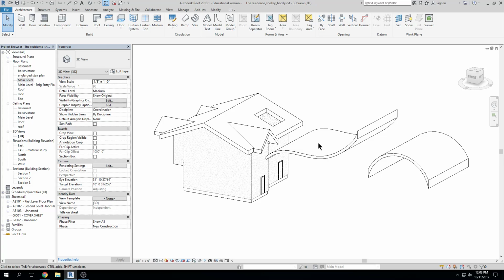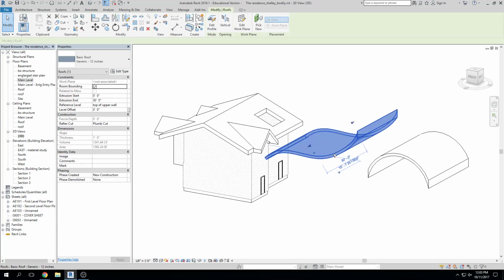So we want to create roofs, we want to create floors, we want to create ceilings, even if we could combine a few of the elements. Like I could probably put gypsum board or wood on the bottom of my roof to show the ceiling below, but I don't do that because then items wouldn't host.